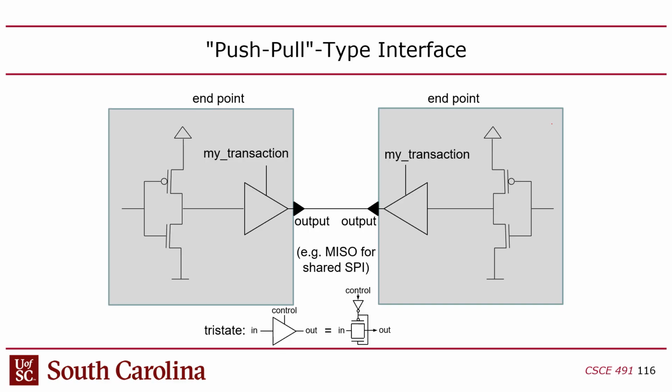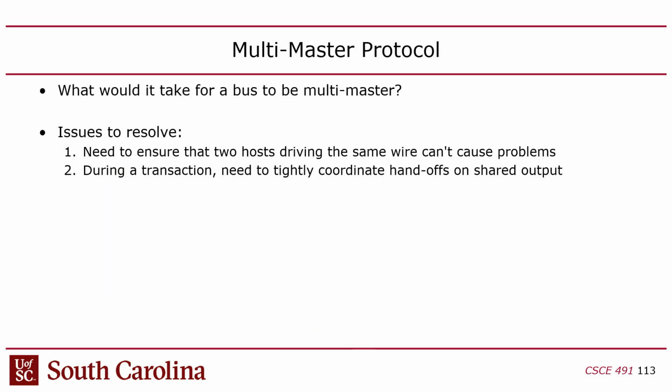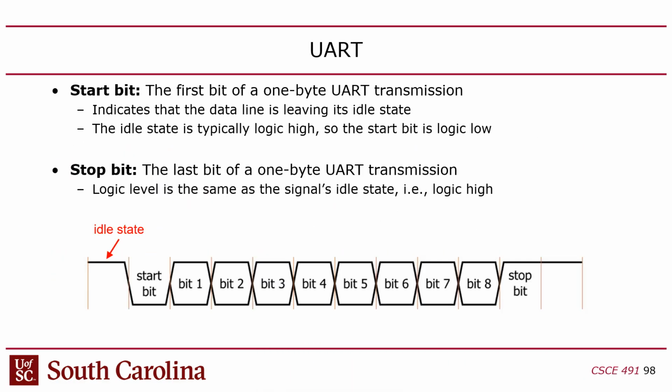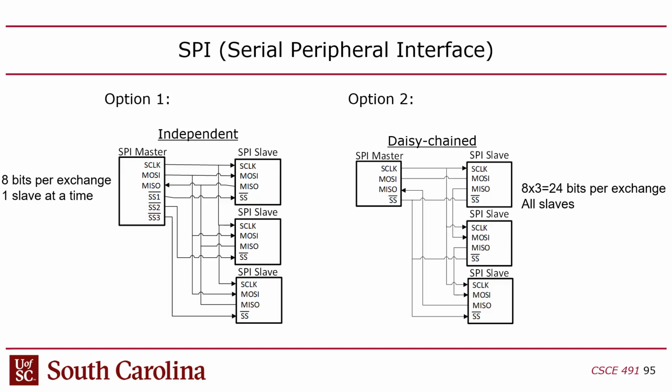So in the case of that multi-SPI thing I was talking about earlier, what would end up happening, I believe, is these MISO connections, the chips would understand, hopefully, that when the slave select is not active, when they're not being selected for the transaction, they would tri-state the MISO, right?